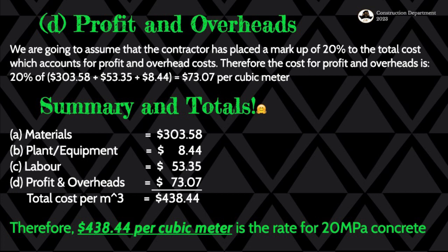If we need to change from this currency to that currency, you also need to factor in that there is a pound per hour, there is dollar per hour. You need to factor in all of it. So you need to know what you're dealing with at each and every stage. So I hope you have understood as you were going through the stages. If you didn't, make sure you revisit the video to understand that. But that's basically the basics of rate build up in construction estimates, how we estimate in the construction industry.